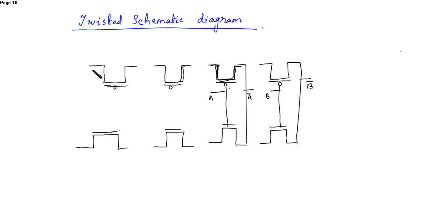So now we actually know this is source, drain, source, drain, source, drain, source, drain. These are two inverters. They are again source, drain, source, drain, source, drain, source, drain. I'm not labeling the sources and the drains because all are in the same pattern. So the VDD are connected. These two will be connected to ground.